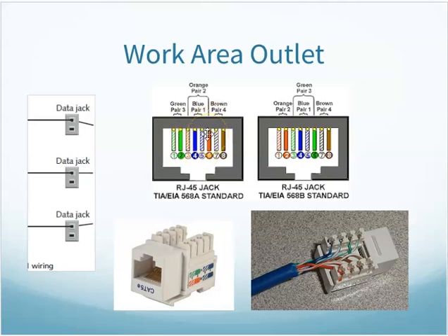So I could plug in a phone jack in the middle and use those middle wires, and the outer ones wouldn't get used in that case. But all 8 then can get used for data. So this pinout looks odd, but it was actually to accommodate phone cables. I could plug a phone into this, use those center 4 wires. But then as I unplug that and plug a data jack in, a modular 8-pin connector for the patch cable on my computer, I'd be using all 8 wires then. So that is the pinout for outlet jacks.